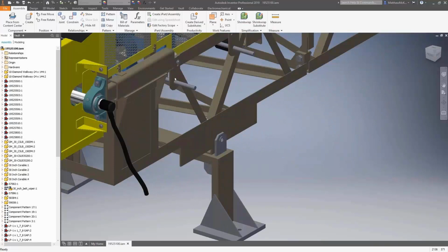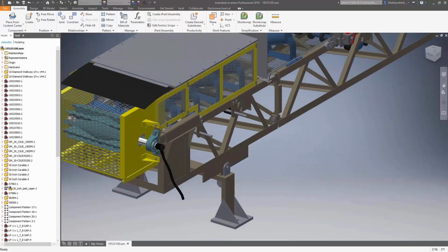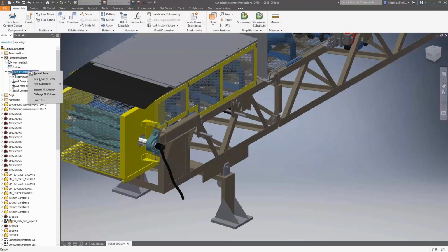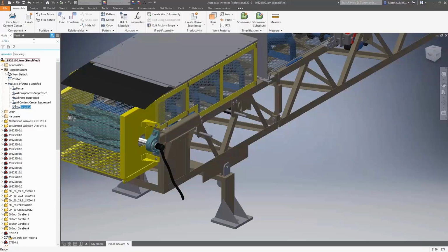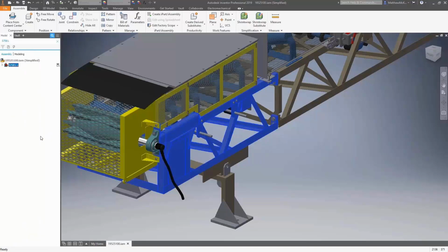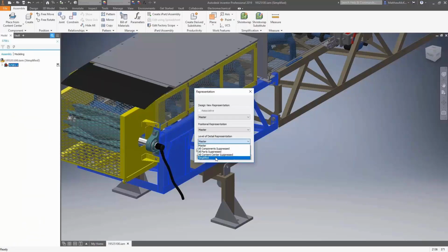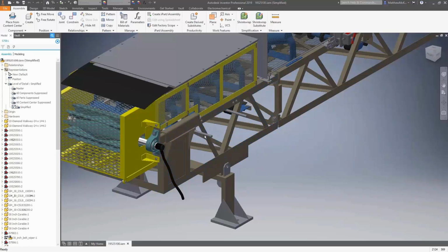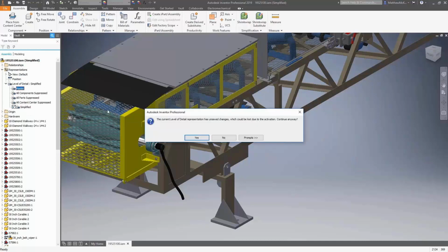And this is good when it comes to working with large assemblies, because we can remove a lot of the detail or unnecessary components inside of a design and improve our capacity to be able to better handle large assemblies. To follow up from this, we'll also create a level of detail at top level assembly called simplified, and we'll change the state or the representation of that sub-assembly to make sure that it is in this simplified state, showing the same view rep, which was the simplified one that we'd also created. So we're linking the two simplified level of details between both states.